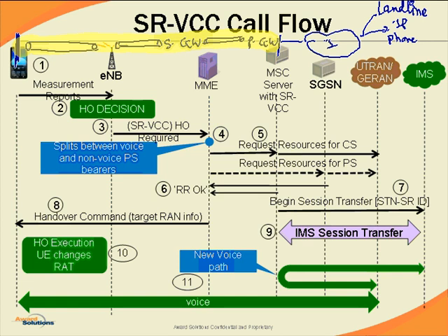Then voice will be through 1X, and data would be simultaneous but through another independent baseband processing block and RF processing block. That would be an initially proprietary implementation by the UE. That is always possible. But from the standards perspective, initially 1X voice and no data. That would be the common scenario.